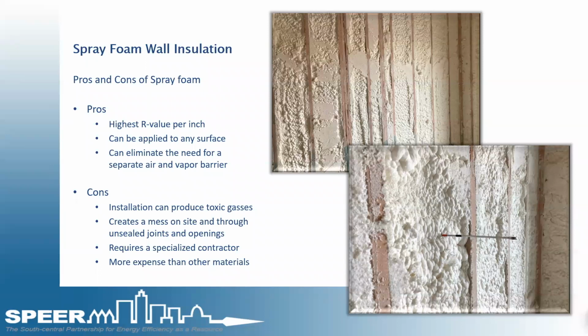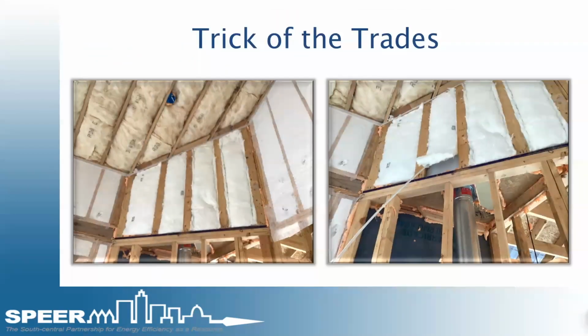But as you see, the divots and the decreased insulation between cavities, if it's too much of a decrease and there's not enough insulation in there, the overall R value is affected, and that should be called out and should be resprayed to meet the overall R value.